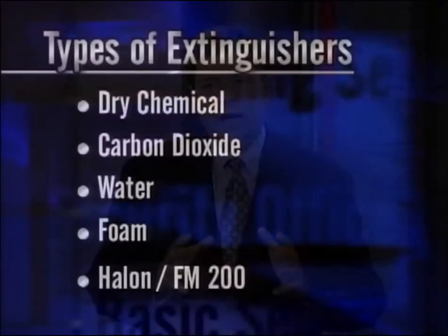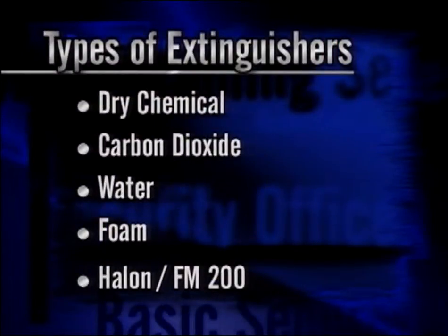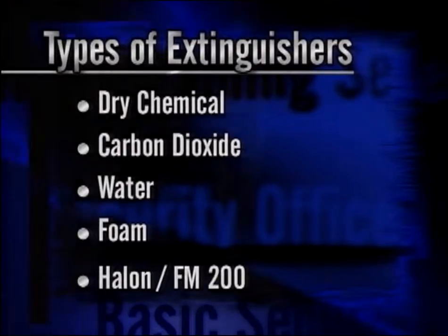Next, halon or FM200. This chemical stops the fire by inhibiting the reaction between the fuel and the oxygen present in the area. They're most often used in high-tech areas where there's a great deal of expensive computer hardware. Now, halon FM200 leaves no residue after it's used, but it's very expensive to install and recharge.